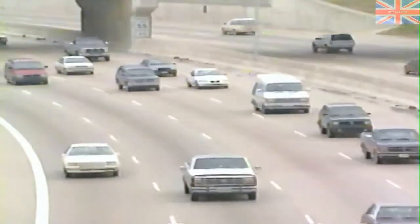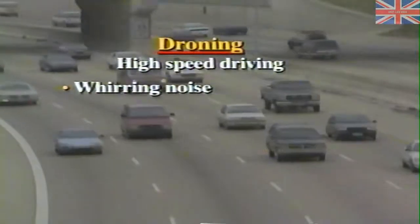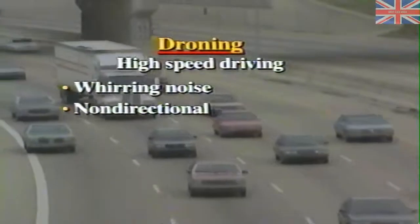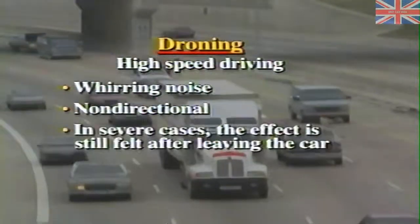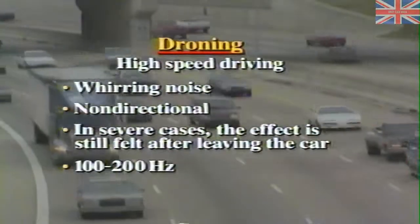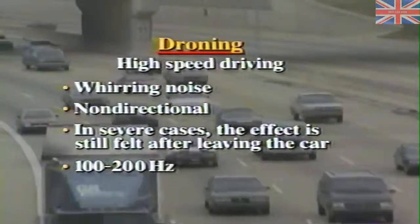During high-speed driving, droning is more of a whirring noise that is non-directional and uncomfortable to the ears. In severe cases, the effect is still felt after leaving the car. The frequency is generally 100 to 200 hertz.